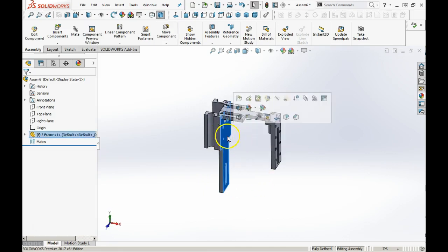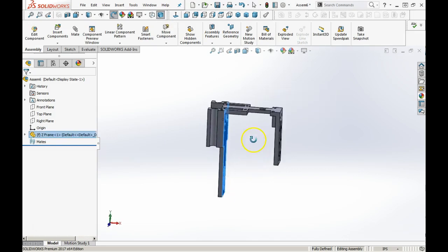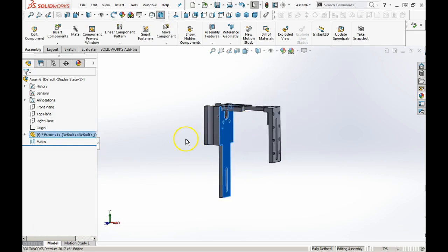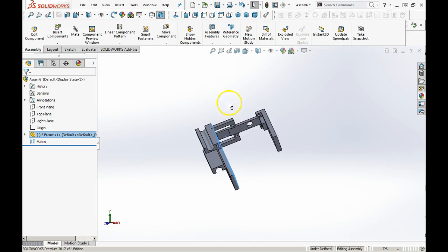If I try to rotate the part by right-clicking and moving it, I can't. Okay, this is the middle mouse button, rotate. And then if I click a part and I try to rotate with my right click, and it says it's fixed, I can't move it. So what I'm going to do is I'm going to click the part and say float. And so now if I right-click it, I can float it around.